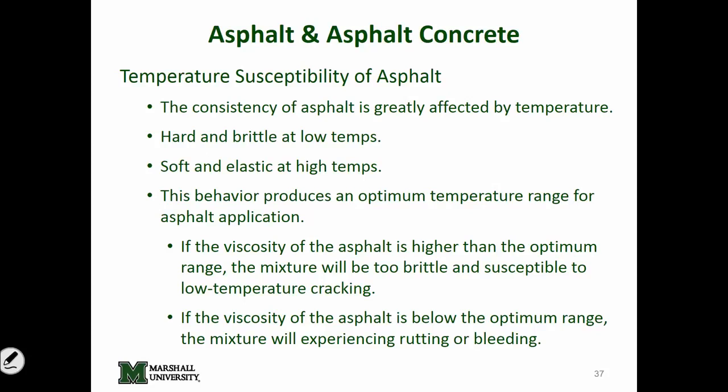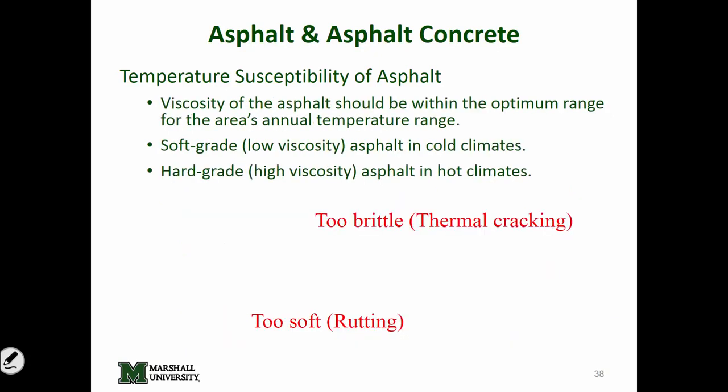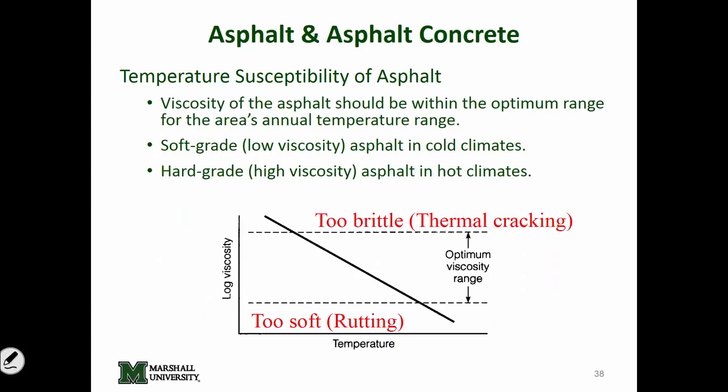The kind of asphalt concrete you use in Florida is not the same one you're going to use in Minneapolis, Minnesota. If you take the asphalt concrete from either one of those to other places, it will fail miserably very, very quick. So you've got to make sure you've got your temperature ranges properly set for this material to work well. Too brittle, you're going to have problems. If it's too soft, you're going to have rutting. So you've got to make sure you're in that sweet spot in the middle there.